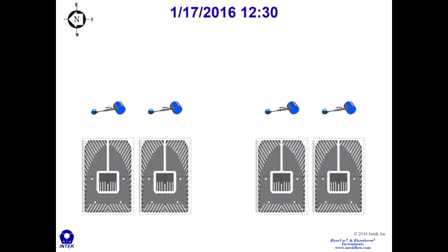This condenser was just newly commissioned, and the performance of this condenser was not where it needed to be. They knew the condenser pressure was above the design value, but they didn't know what was causing it. They didn't know if it was fouling, air and leakage, whatnot. What they really wanted to know is if air and leakage was affecting the condenser's performance.